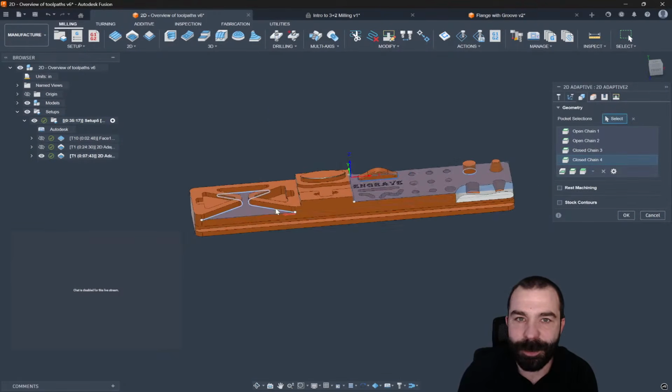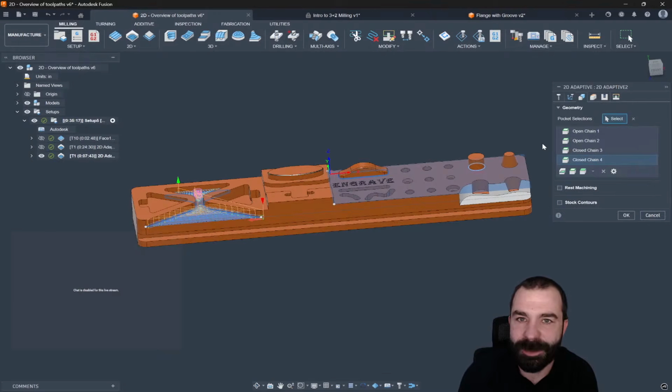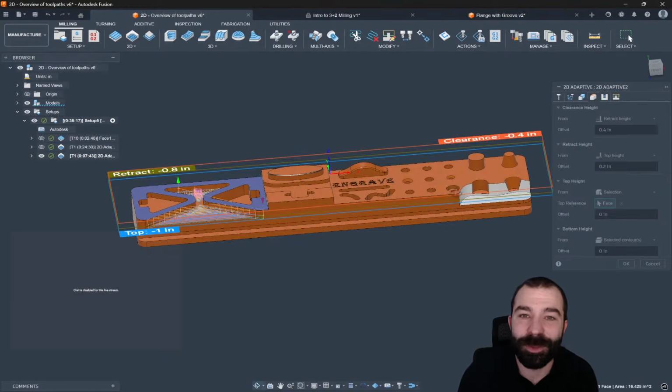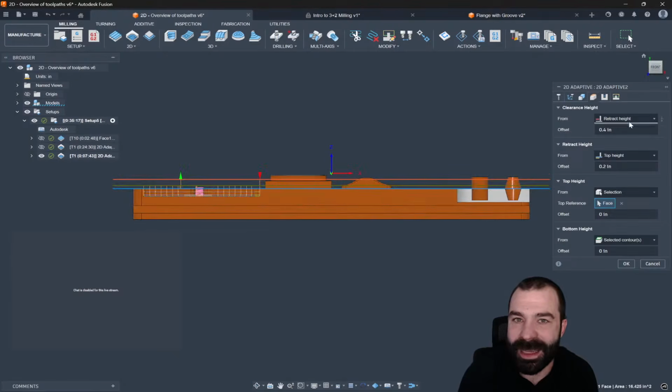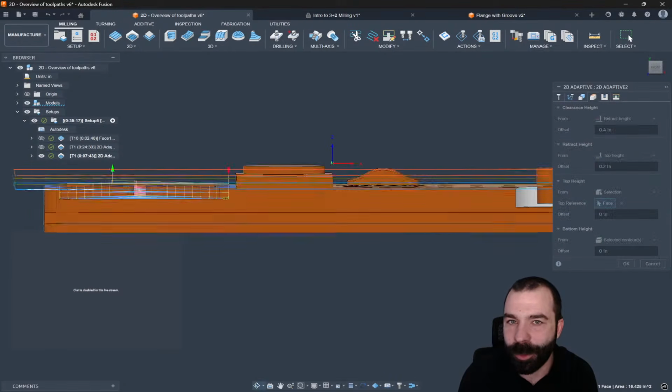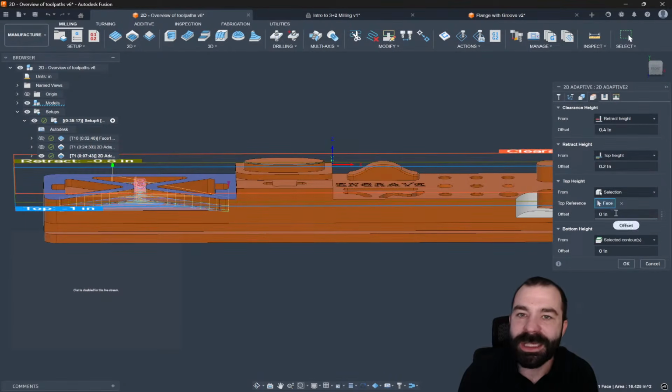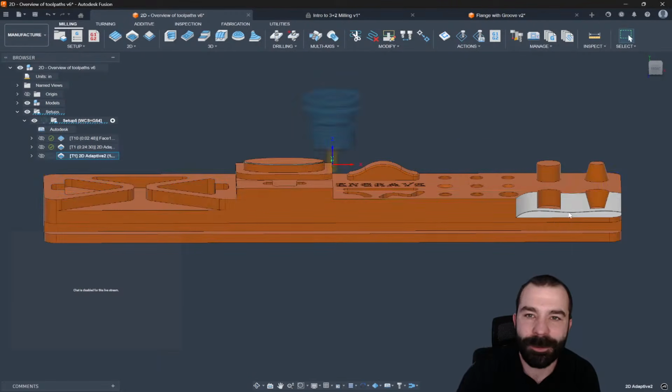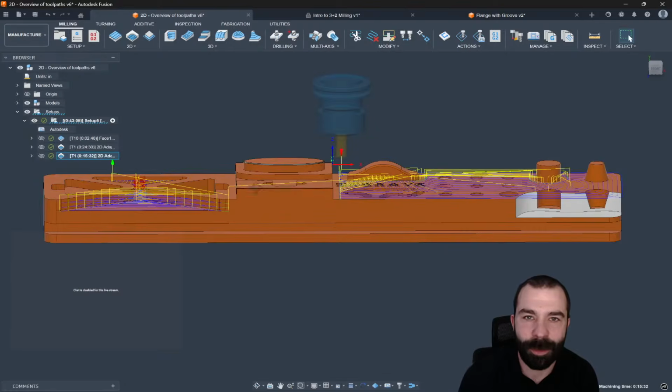We gave it multiple regions. We should be machining both sides. But of course, what's now haunting me, which leads me into a really valuable item here, is that my top height reference is below this floor over here when they made this model. So, for demonstration purposes only, we're just going to raise her up a little bit so I can get a toolpath on both sides.